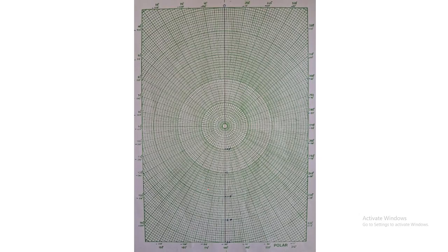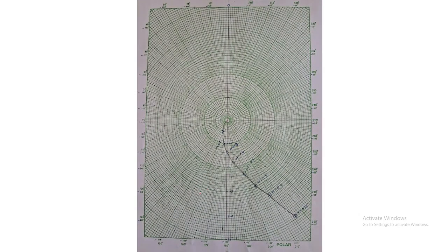For omega equal to 0.35, your magnitude is going to be 2.2, and for this magnitude I will be getting minus 144 degree. So minus 140, 141, 142, 143, 144. So here this is going to be your omega of 0.35: 2.2 and then minus 144 degree.